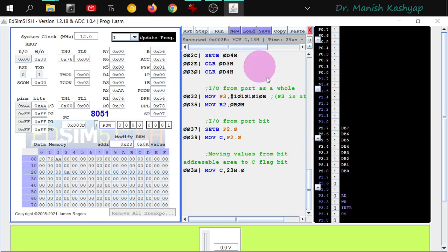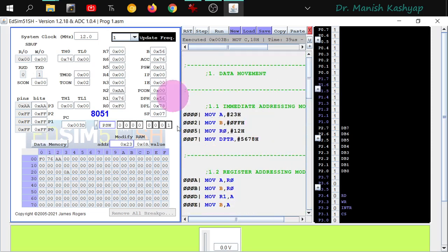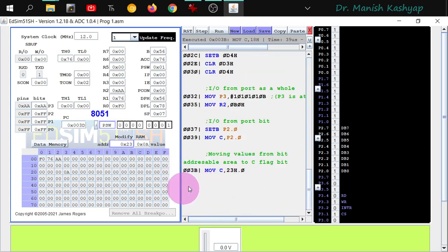So this programming portion was essential for strengthening our understanding of this 8051 architecture. And one important point to note is that after the execution of this complete program, you won't ever see any halt statement in microcontrollers. Why is that? Because usually a microcontroller is attached to appliances like washing machines and ACs. And whenever you start it, you do not want the program to execute and just stop. For example, if it is the air conditioner, it has to continuously sense the temperature.